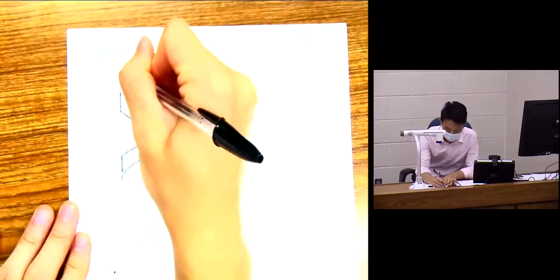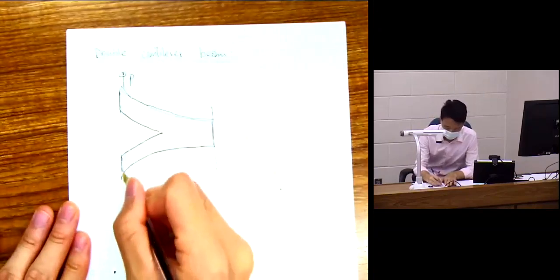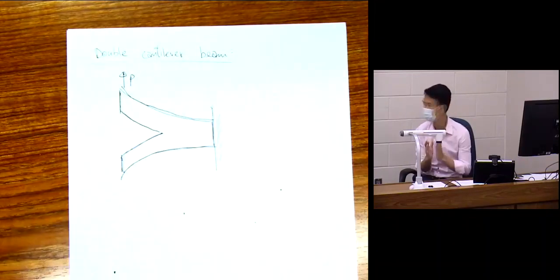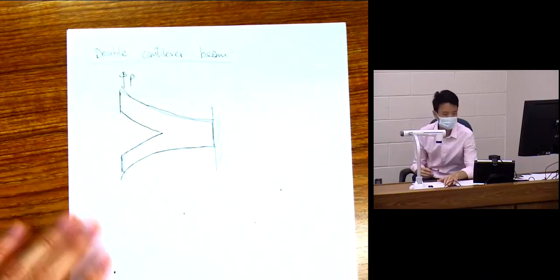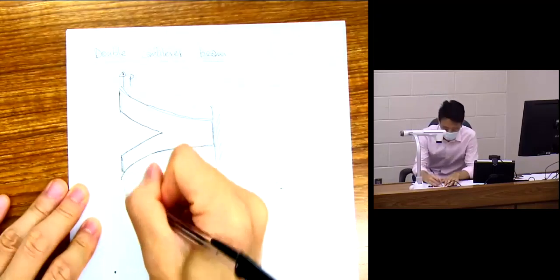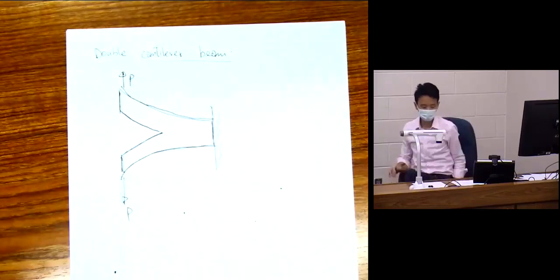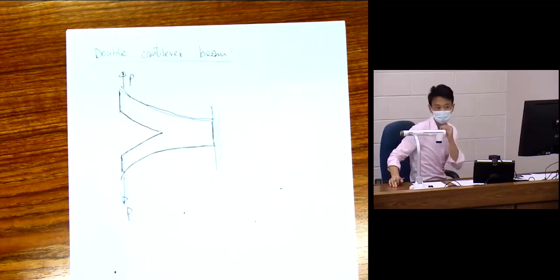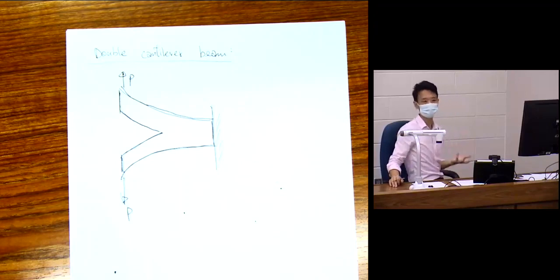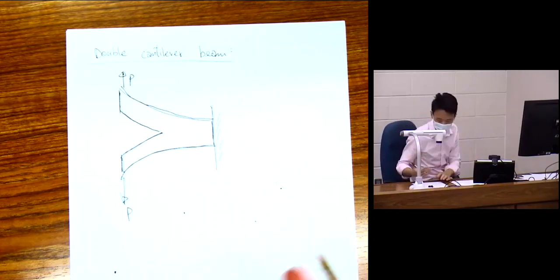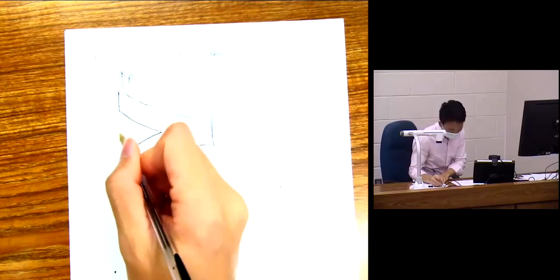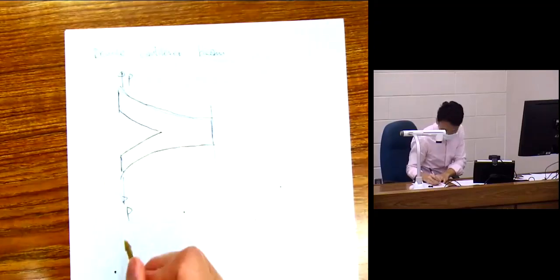So you can look at this. This is the crack, right? There's a pre-crack in your solid already. Now, is it going to crack further under the existing load? So think about this. This is like a cantilever beam problem, and so we actually know how to solve it, because we know beam theory, and we know how to solve the stress field and the displacement of the whole beam.